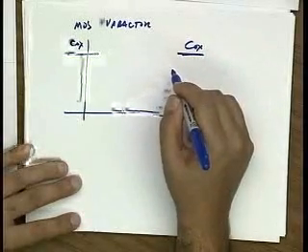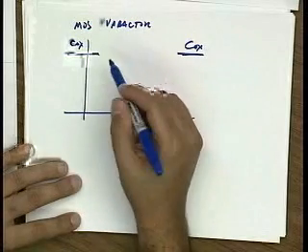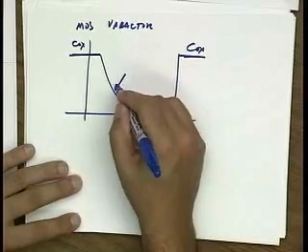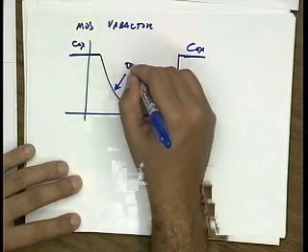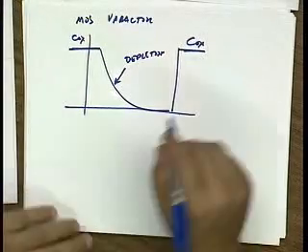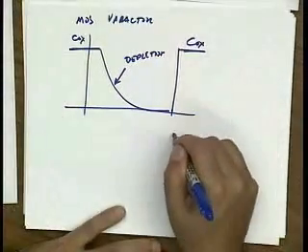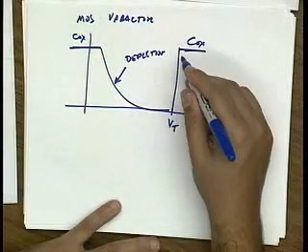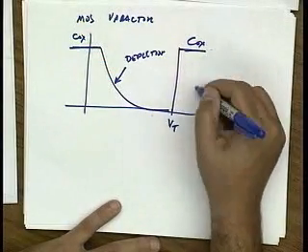In a simple model, in this region, we call depletion. This is before a channel has formed. So in this very simple model, we assume that at the VT of the device, the threshold voltage, almost instantaneously a channel forms and we get this Cox capacitance.